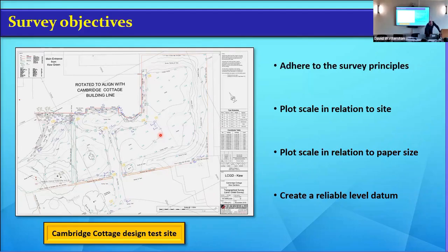But again, if you look at the scan data, it actually sees right through the window. So I'm surveying stuff within the building, which is interesting. But again, if you were using a scanner and they used it to do the topographic survey or the land survey, that'd be fine. But you would generally employ it to do elevations, because to survey the elevations on there, you can do it by photogrammetry, rectify it, or you can do it with scan data and then trace around the line work. But again, the scanner, if you were going to do a refurb in this whole building, you would scan it outside, along the faces of the building and inside. So you'd do everything with the scanner.